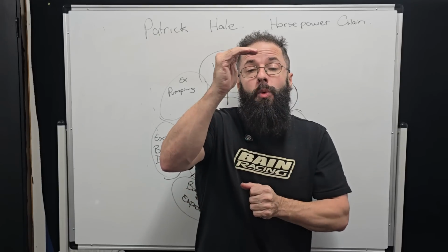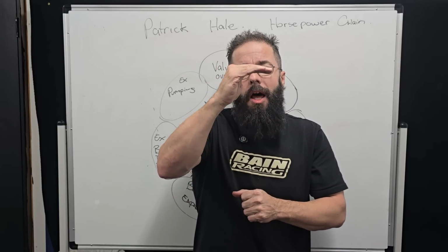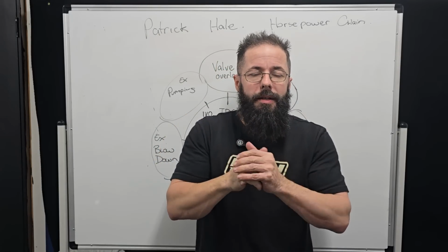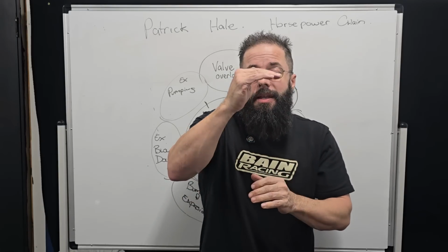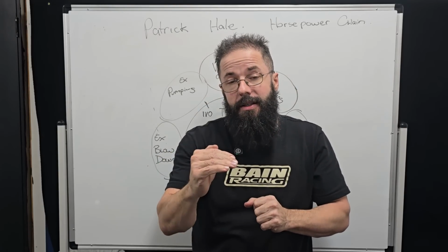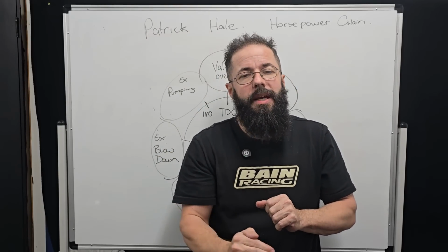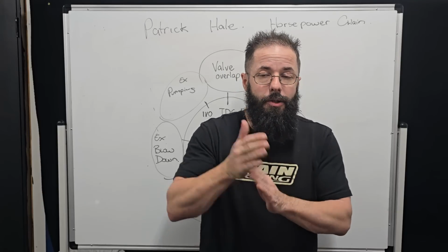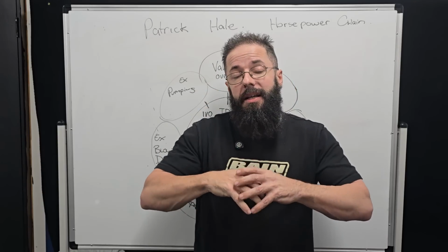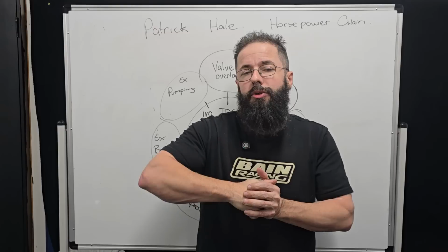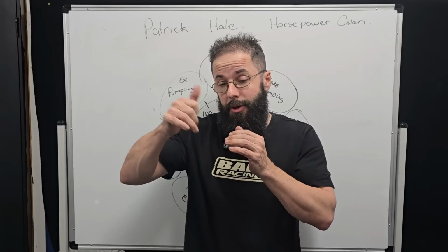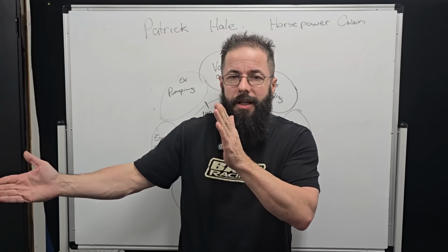The piston will start off slow at TDC because we have a dwell depending on rod length, and then the piston accelerates to mid-bore and then slows down after that and will turn back around. So we're actually blowing it off and then allowing that expanding gas to rush out the pipe and cause that exhaust pumping, that high velocity that we'll see down.